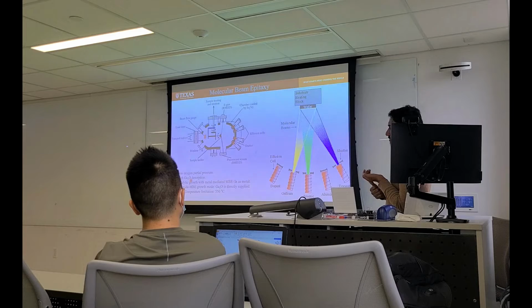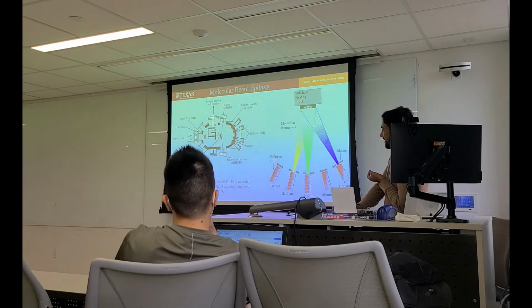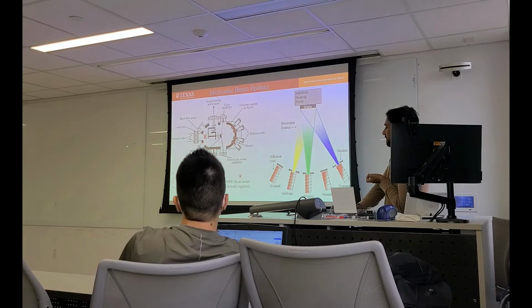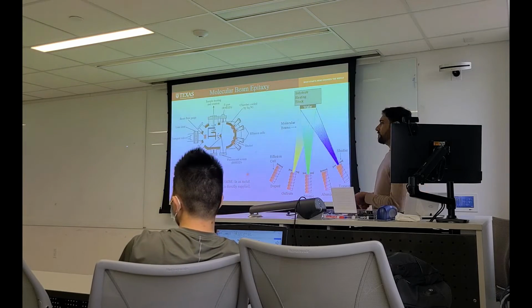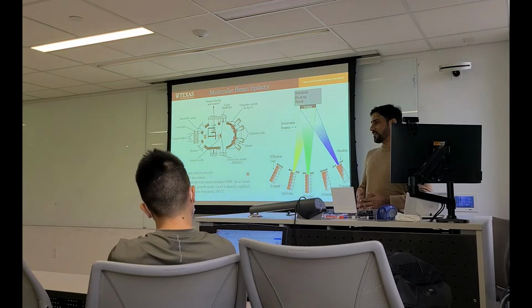So you have to tune your growth conditions to control the desorption, but still, because of the high vacuum, there is a limitation. Researchers did some modification in MBE, like they investigated catalytic growth with metal-mediated MBE. Catalytic growth means that whenever you use metals, they act as a catalyst. Suppose gallium nitride is grown at 1000 degrees centigrade.